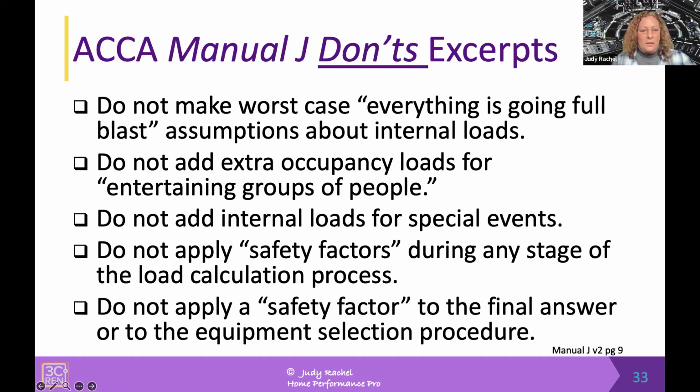Don't make worst case, everything-is-going-full-blast assumptions about your internal loads. You don't add extra occupancy loads for entertaining groups of people. The load calculation is for permanent full-time occupants of the building. Supplemental conditioning is necessary for those large groups of people. And that's what needs to be told to anybody who is asking you, well, is my home going to be comfortable for all the parties that I love to throw?